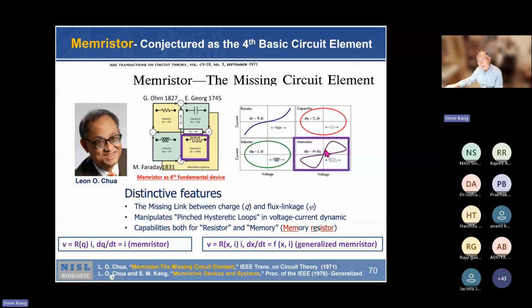And then there can be a change of state. If you drive up, say, voltage here, you follow this curve. And then if you exceed what is called the set voltage, it will follow this curve. And if you decrease, it will follow this curve. And if you try to increase more, then it suddenly changes to this curve. So you can circulate this Lissajous figure, for instance.